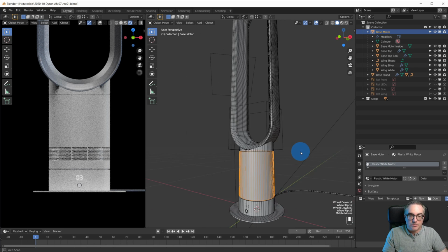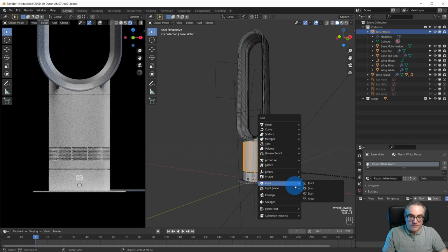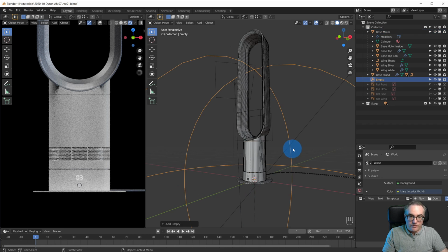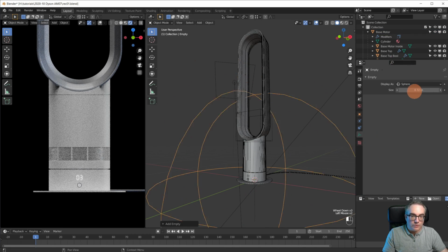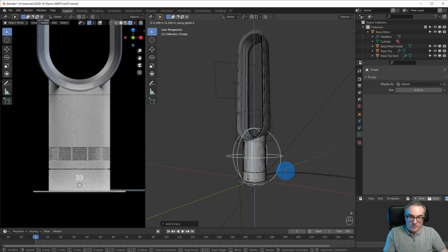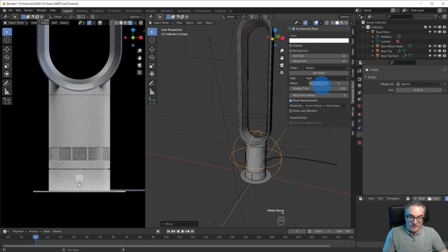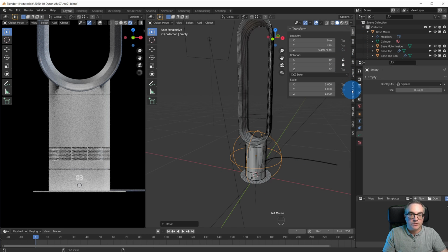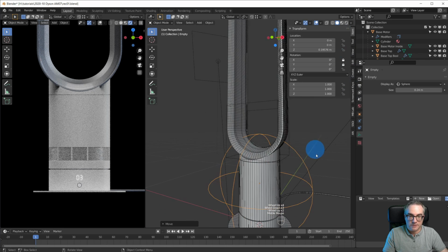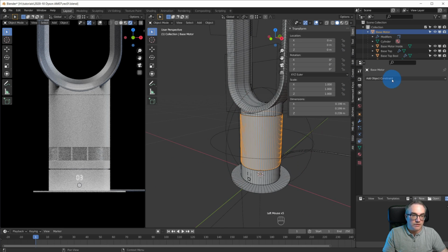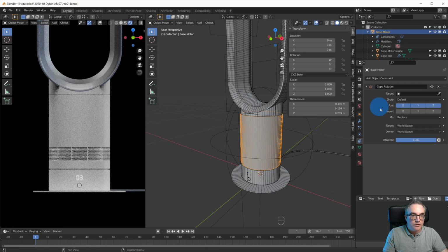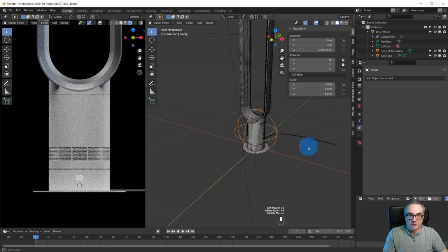So now, how do we want to do this? We should add an empty sphere. This is a big empty sphere. Make this smaller. Bring it up to here. And then we can fix the rotation X, Y, so we can rotate on the C. And we can take this guy and maybe add a, where the hell are they? Constraint, a copy rotation constraint of this empty. I mean, you don't have to do this, but now you have this sort of handle here.